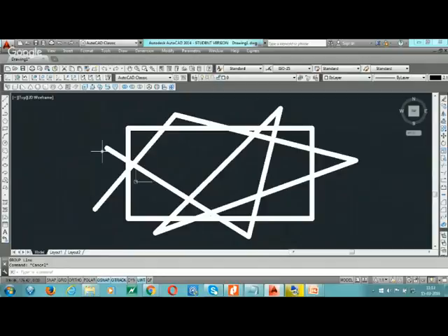So what you will do is, you have to decide first how much portion you have to cut. For that, what you will decide is its boundary lines, right? So in the trim command, you should first define the boundary lines, and then the objects which you want to trim, right? Mr. Pal Singh did it by selecting all the things at once and defining the boundary lines.